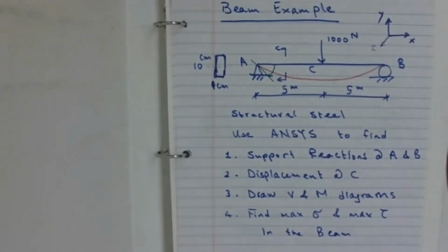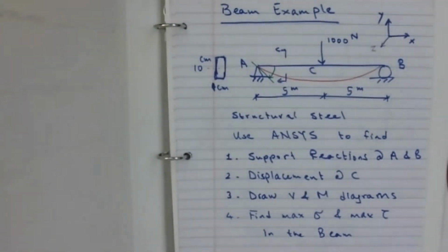All right. We would like to continue looking at ANSYS Workbench. So far, you have used it for axially loaded members. And remember the element we used when we used the line concept was a beam element. A beam element is capable of capturing the behavior of axially loaded members, loaded in bending as well as in torsion. So far the application was on axially loaded parts.